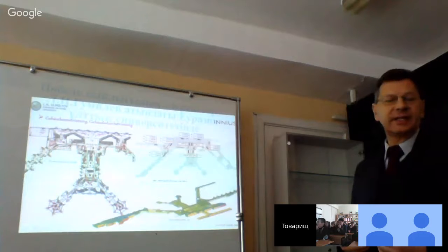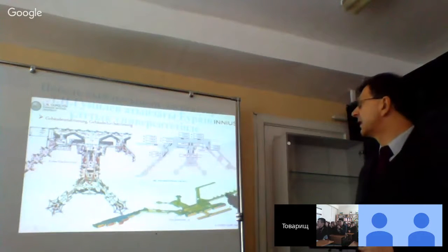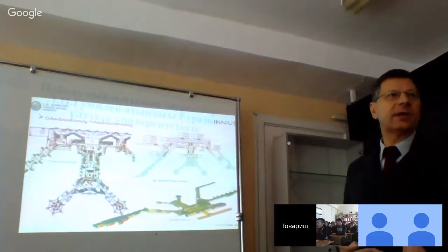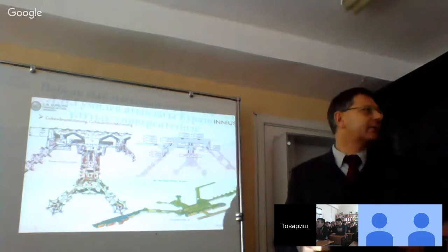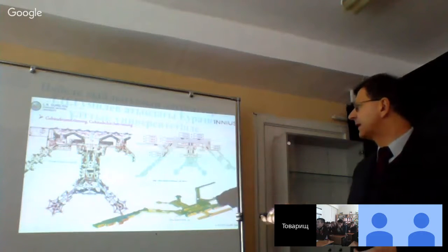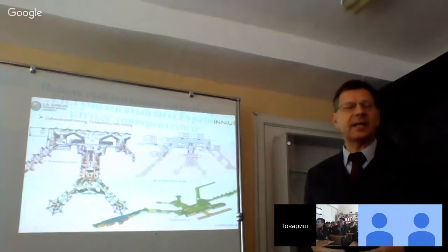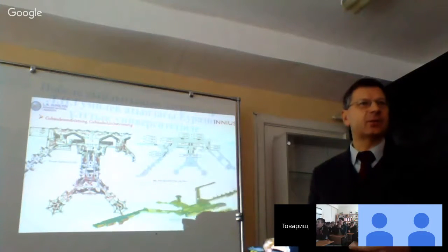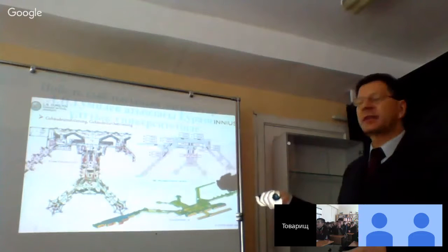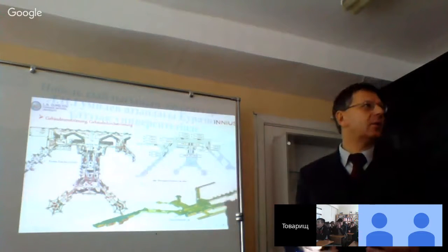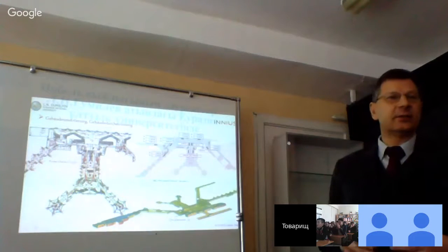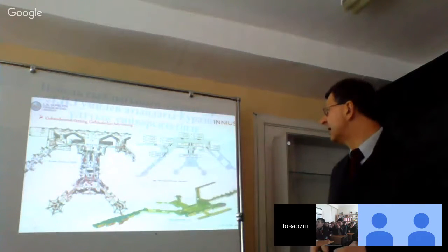We include in this calculation the situation on the entrances. You know, if you have an airport, there's always traffic from the persons from the outside to the inside of the building. You have always the situation that you have airplanes and the gates open, and that means at the end the building is open from the entrance to the gate, and depending on the wind which you have on the facade of the building, you get an airflow through the building.